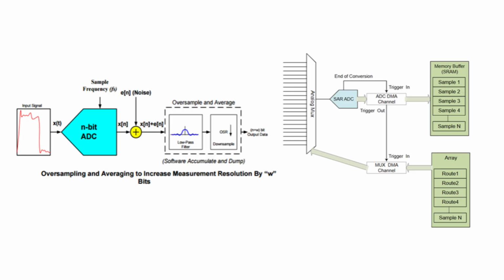Yep. Then you take all N of those raw digital readings, add them all together to get a big sum, and then you average them. The averaging is typically done very efficiently by just right-shifting the accumulated sum in binary. Shifting bits to divide. Clever. How much can you actually gain in terms of resolution by doing this? Is it magic? It feels a bit like magic, but it's based on statistics and noise.